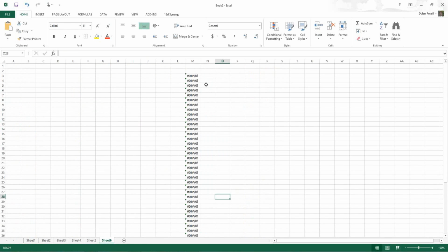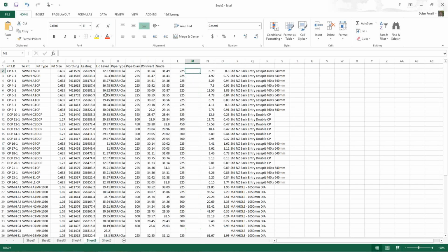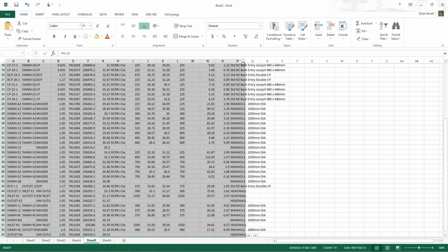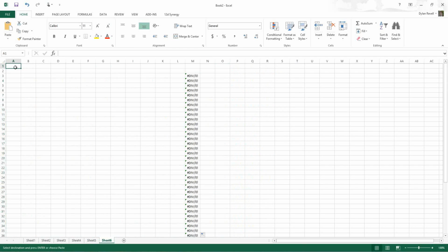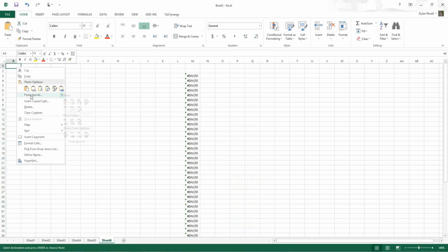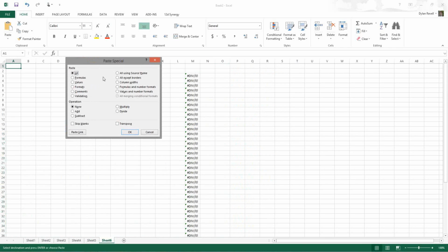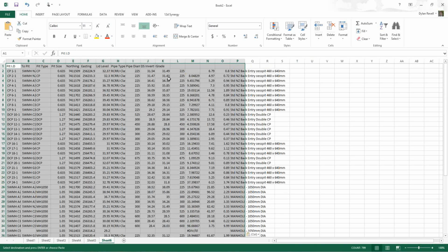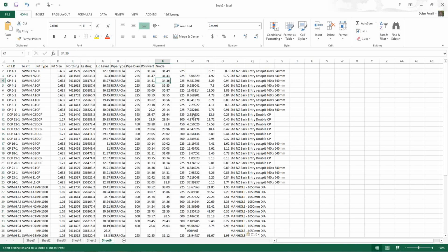So this may be your pre-formatted spreadsheet workbook that has all of your formula for checking in it. So what we recommend is you have a workbook that you take the 12D information into and paste that directly out of 12D. Copy it from that paste worksheet. And when you enter that data into your pre-formatted workbook, do a paste special. And under the paste special, we want to take the values only, and we want to skip any blank columns. And if I go OK on that one, that will retain any formulas that are in the worksheet, and adopt those and take them on the pasted data.